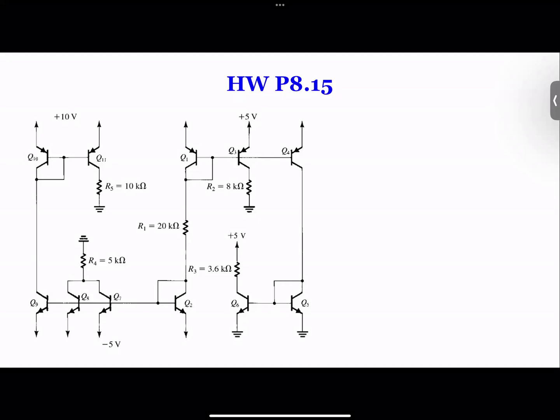So you were given the bottom, you give -5 volts. Here you can give the ground, and the top you give 5 volts. But in the middle, you have a bunch of stuff. Like for example, from here to here, it's 0.7. So we can find that one, because again, we assume everything is in linear mode, right? So because this is connected, we found here. And this bunch of stuff, we cannot find it because, even though we know from here to here is 0.7, we don't know here, right? So here, this is ground, and this got to be 0.7, so we found the voltage over here. But then we got to stop because we cannot do anything to the above.